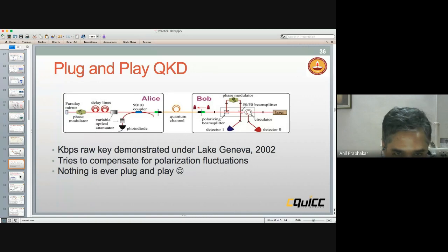The information is again sitting on this phase phi A and phi B. When phi A and phi B are equal, then you get detection coming down on port 1, and when they are unequal, you will get detection coming down on port 2. How do you make sure it comes on port 2 is another component out here called a circulator, which basically the laser that comes in circulates and goes down there, comes back, and then it interferes out here. So this is what is called a delay line interferometer, and this interference will then cause it to come either detector 1 or detector 0.